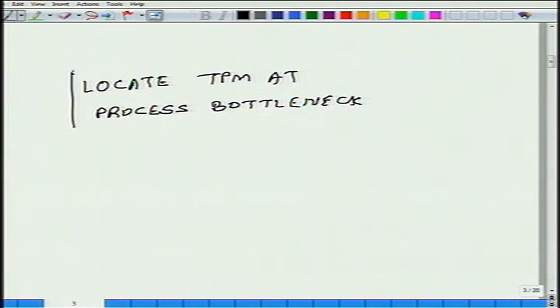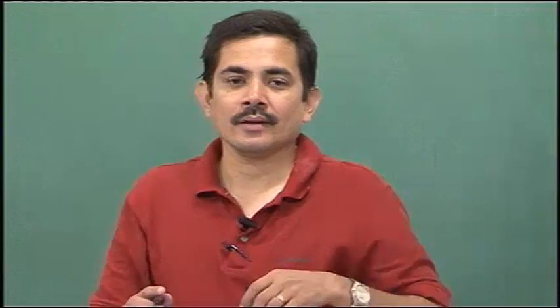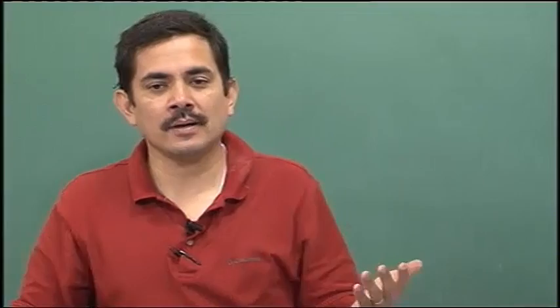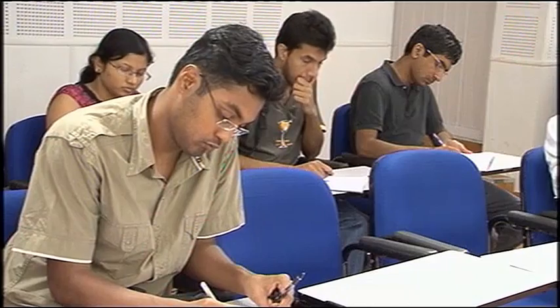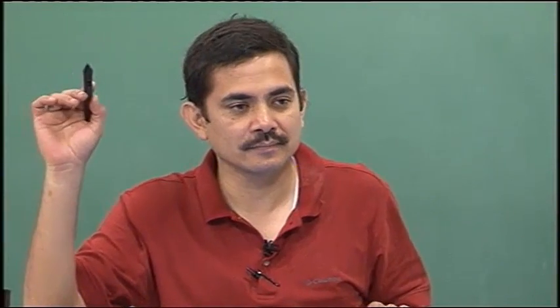Okay. We have already seen, once the location of the throughput manipulator is fixed, the rest of the control system follows automatically: level control, temperature control, pressure control, composition control. Yes or no? However, I do need some extra information. What is that extra information? What is my capacity constraint?